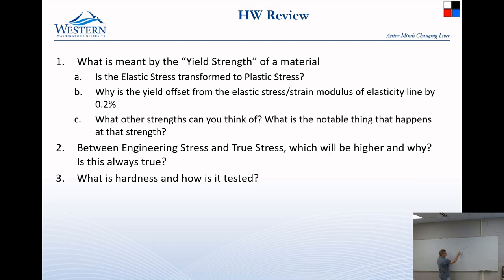And especially right up here at the top, a lot of things happen as it is moving into the plastic region, lots of little wiggles and whatever. So it'd be very hard to define it. This is just a little easier to define. You can take an average of this entire line, and then you can offset it by 0.2% and figure out where it's going to be.